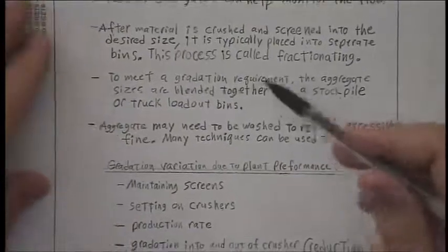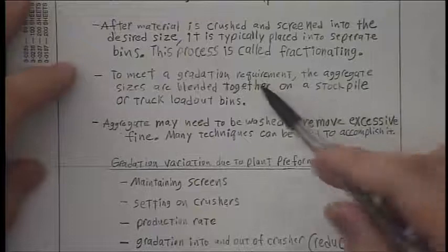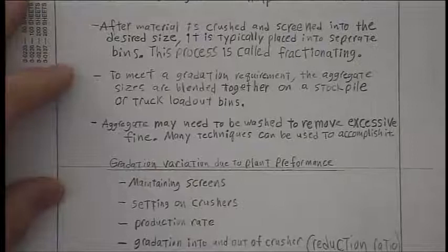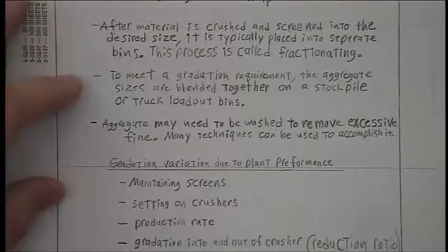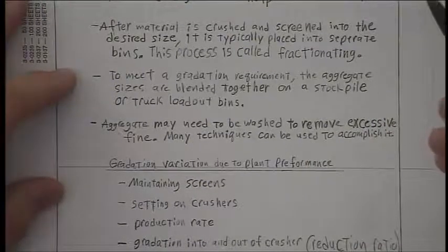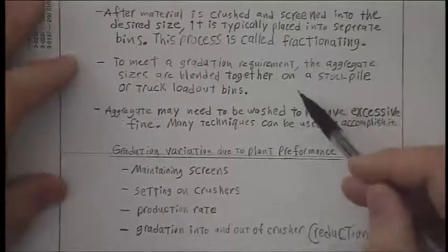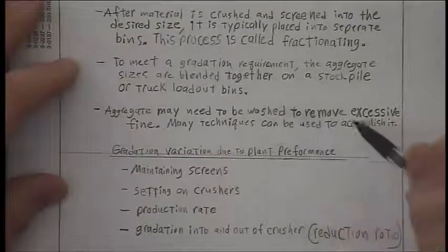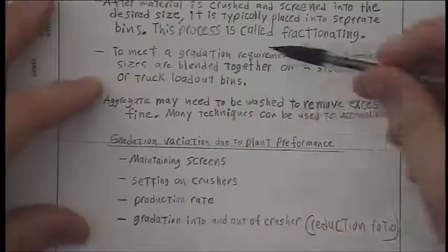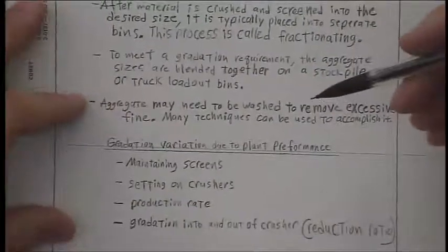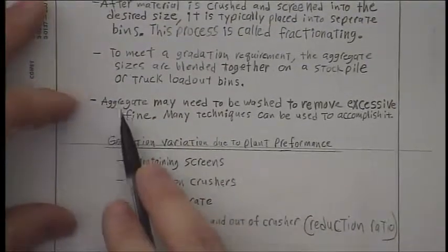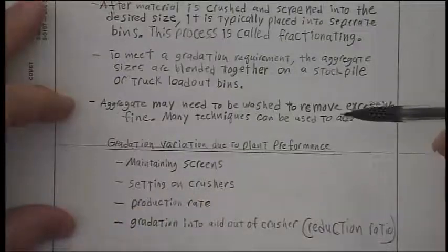It's real important for a quarry to meet gradation requirements. Whether you're talking about asphalt or concrete, contractors require different gradations for their application. So it's extremely important to be able to blend different aggregate sizes together, either to make a stockpile or on your truck-out bins. And one thing I didn't mention is that sometimes you need to wash your aggregates.